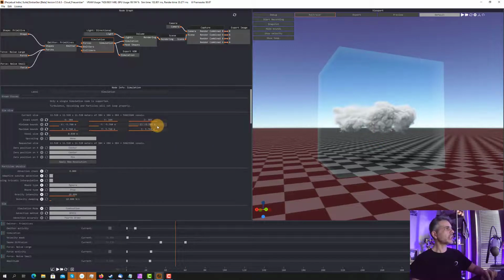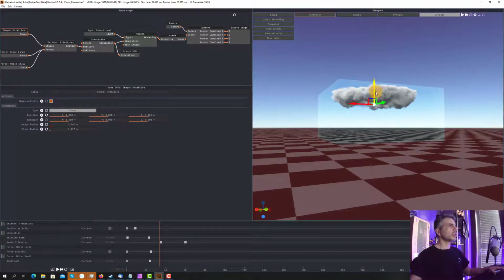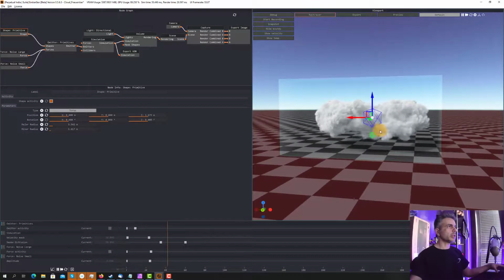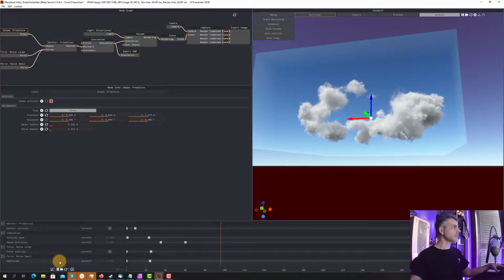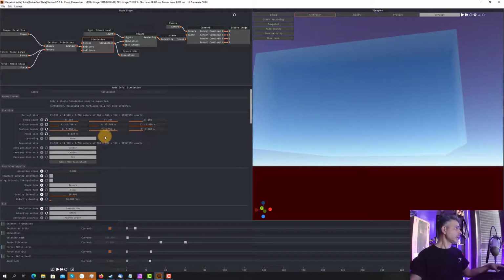If you have more GPU memory, obviously it's less complex, but again, it is not useful to have voxels that are not used. Okay, you see that we have now 5 gigabytes of memory used, and that's really better. So we can move the cloud down, and that's really faster than before to render and to simulate. Okay, we can go back there, and maybe we can go to have a higher quality. I mean, because we have a little bit of gigabytes free.